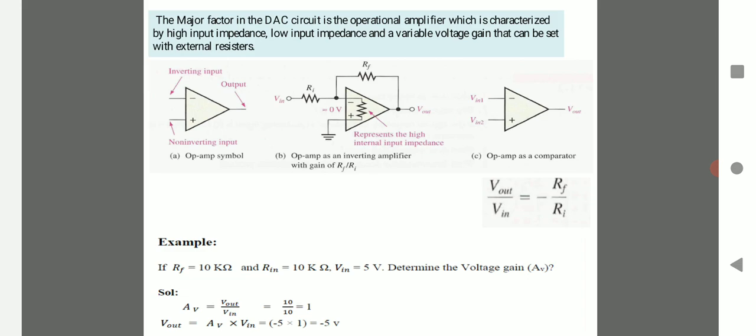Analog signals are continuous and can take an infinite number of different voltage values, while digital circuits, on the other hand, can be high or low, logic 1 or logic 0. So it is necessary to have an electronic circuit which can convert between the two different domains of continuously changing analog signals and discrete digital signals. Basically, an analog to digital converter takes a snapshot of the analog voltage at one instant and provides a digital output code which represents the analog voltage.